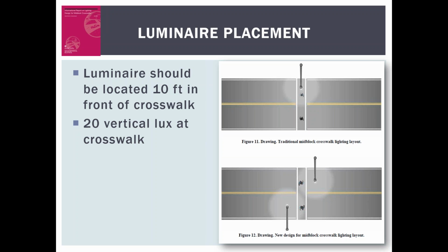I think you've seen a lot of examples of where agencies are doing audits and field investigation. They're probably typically doing that during the daytime hours, and I think that based on what you presented here, it seems that a lot can be learned by looking at conditions in nighttime. Yeah, I've not been on a road safety assessment where we haven't done a nighttime inspection as a part of that. And same thing when you're doing school assessments.